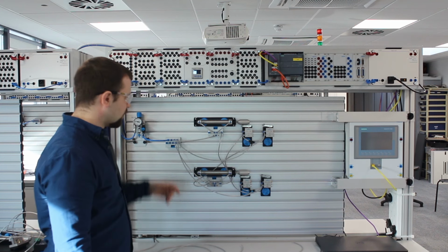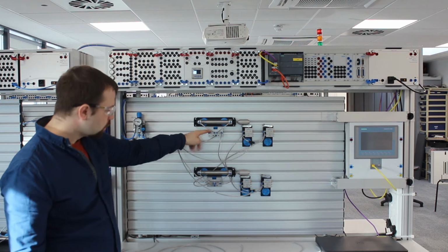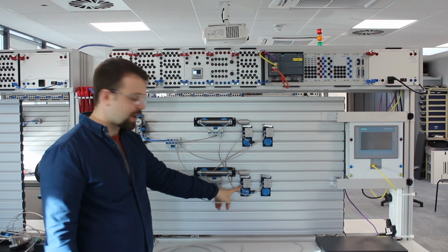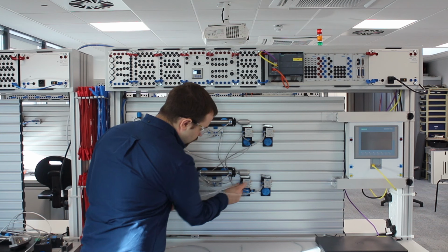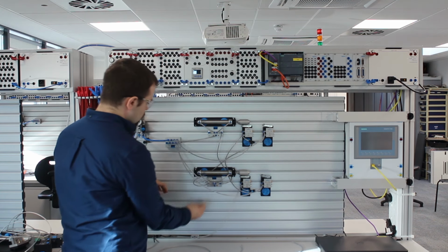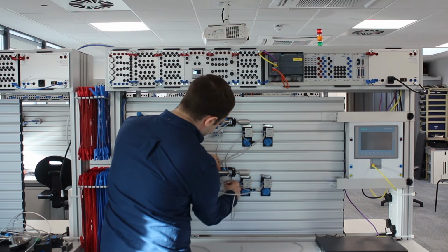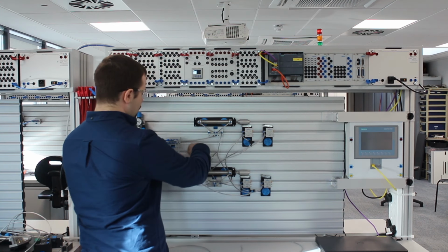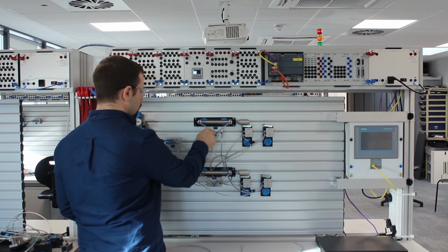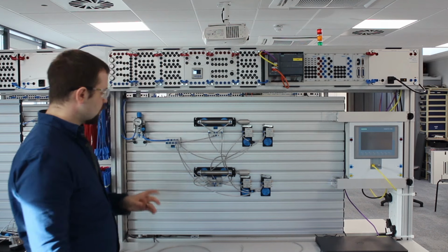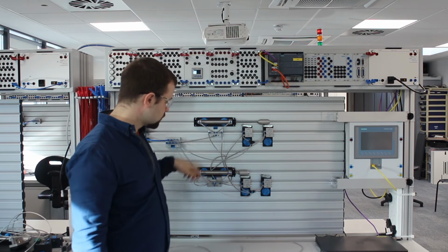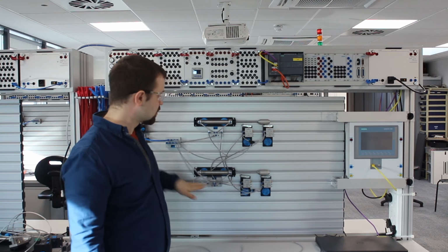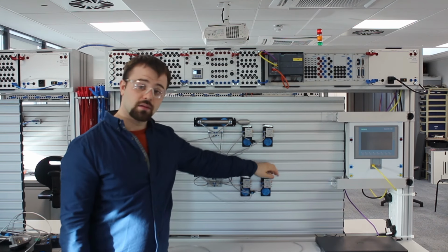Well, how do we make it start? We need to activate 1/4 using the last switch and the last action we had, which was this down here. So, my final pipe will run from port 2 up behind the cylinder and into the 1/4 of A. So all of this has worked. We will have A+, B+, A-, B-.